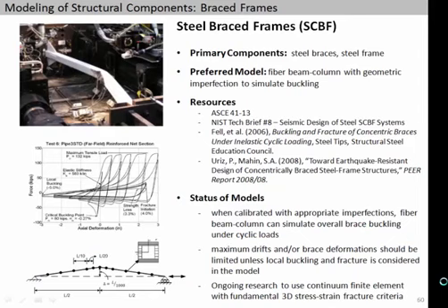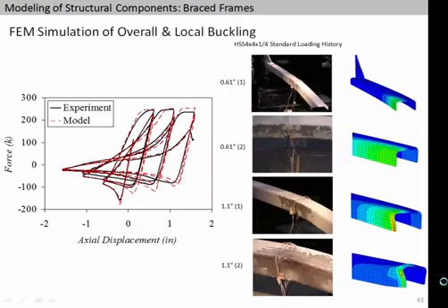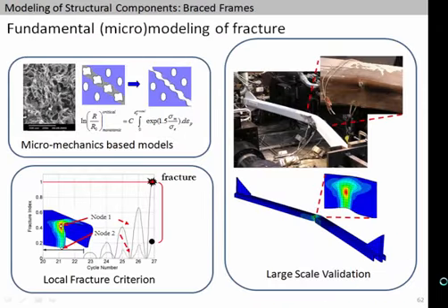I wanted to talk about steel braced frames here. The next couple of slides talk about brace buckling. I think, one, in the interest of time, and two, if you have a new tall building, I don't think you want a buckling brace in it, okay? So you can model those things, and we have neat models to do that, but let's skip that.